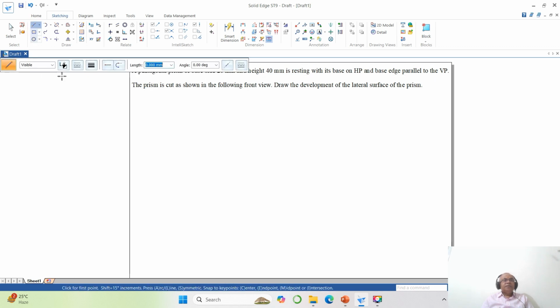So go to line, select the line width as 0.05, take an arbitrary point and take 20, angle is 0, then 20, angle is 72, then 20, angle is 144, then 20, angle is 216, then 20, angle is 288. Now I need to find the center of this, or not, because nothing has been given about the axis, so you need not find the center.